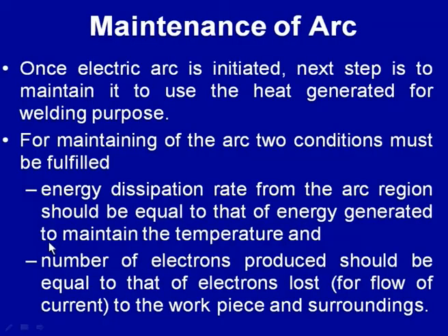So, one condition which is important to be fulfilled for maintenance of the arc is that the energy dissipation rate from the arc region should be equal to the energy generated to maintain the arc, so that the temperature within the arc can be maintained and the required thermal ionization and other things can continue to happen for development of the charged particles in the arc region, and the arc can be maintained.